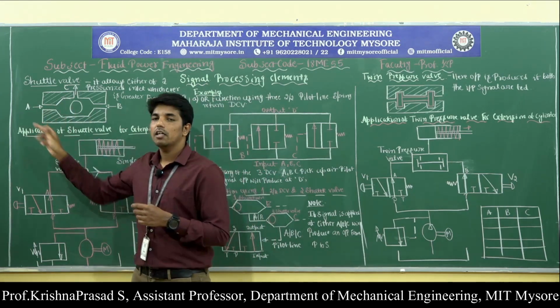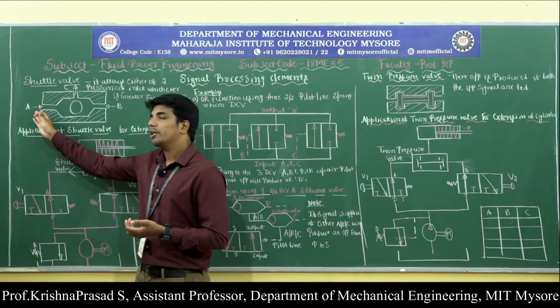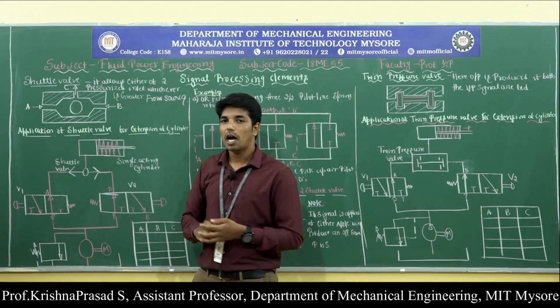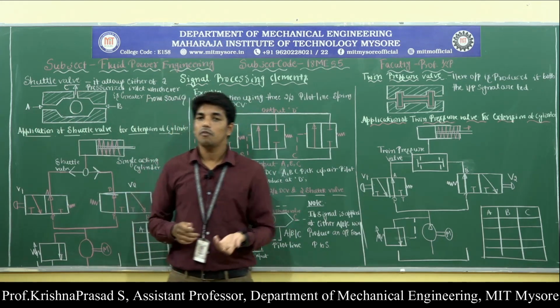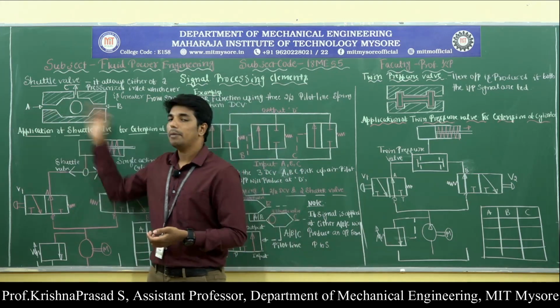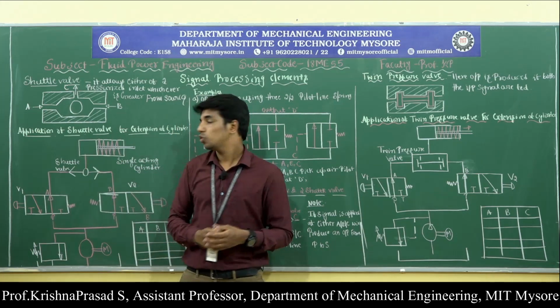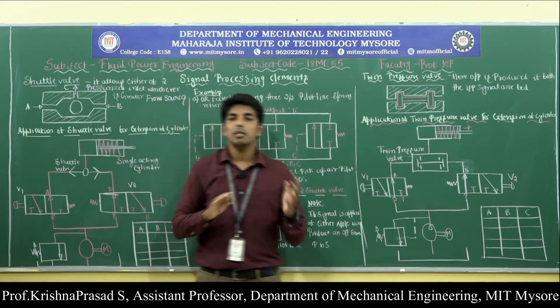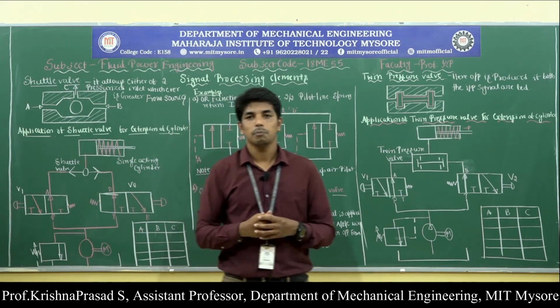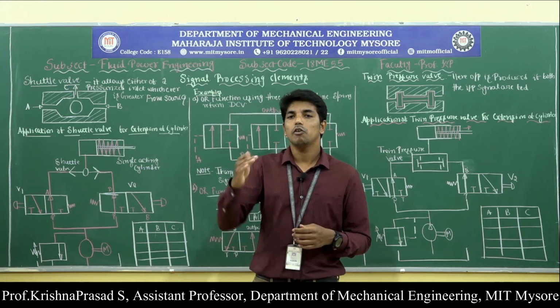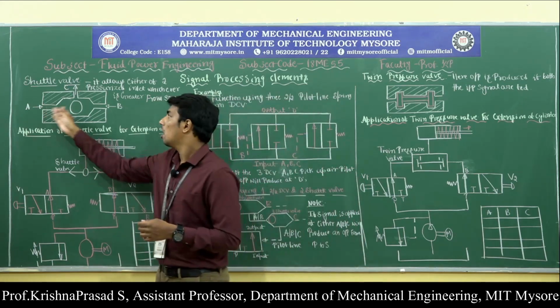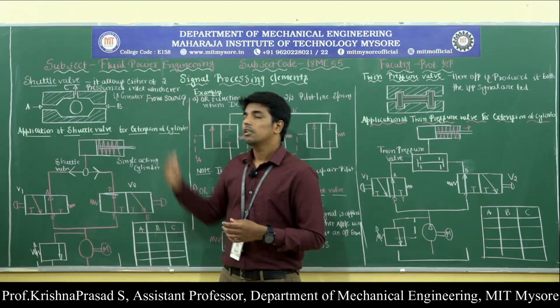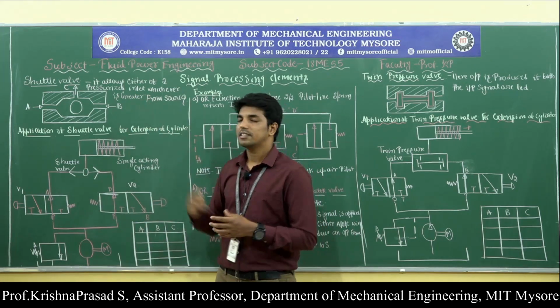The pressurized air may be coming from inlet port A or inlet port B, or from both inlet ports A and B, whichever has the greater source. Then the ball will shift to the opposite side and block the other inlet port. Then air will flow from the inlet port to the outlet port, and the output is produced at point C.